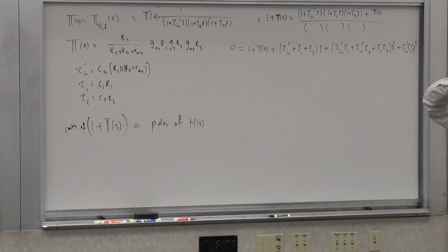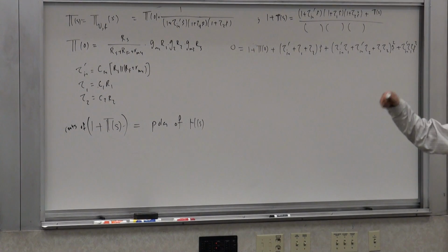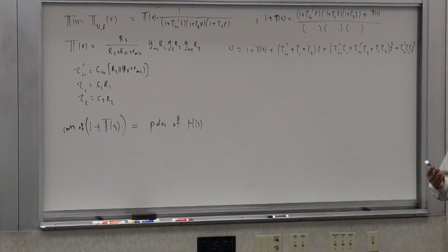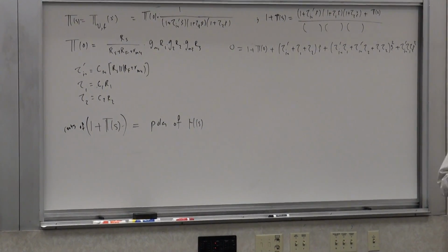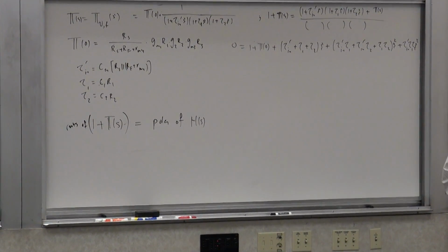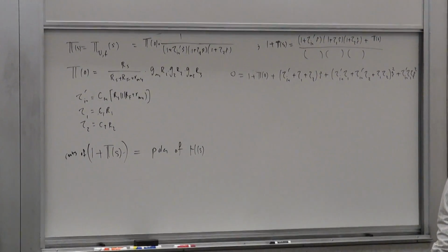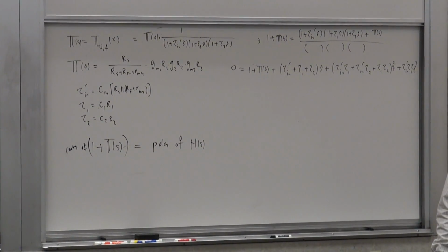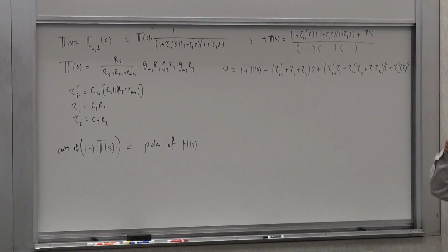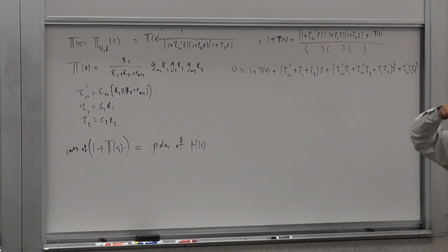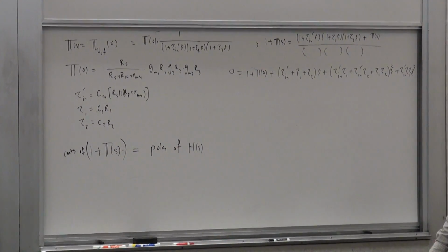When I had an exponentially growing sinusoidal response from a linear system, what did I have? What can you say about it? Right half plane, yes, but we can say even more than that. Can I have real right half plane poles? No, they have to be complex. You have to have at least one pair of complex conjugate poles in the right half plane to get sinusoidally growing exponentials.